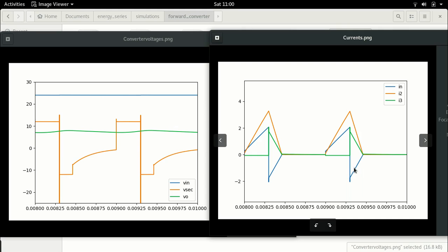So now current flowing from the battery is negative, which means current is flowing into the battery, while current flowing from the tertiary winding is now positive, right? And you can see these two are roughly equal to each other. Now you see here that this current decays to zero, because remember, the energy is eventually dissipating back to the battery, which means the battery is absorbing this power, and therefore as the energy decays, finally the current will decay to zero, right?